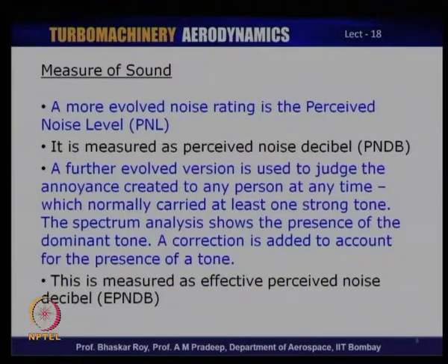Typically, the noise is nowadays measured in what is known as noise level, which was from the science of acoustics, but it is measured now in what is known as perceived noise level or PNL, and it is measured in terms of perceived noise decibel or PNdB.